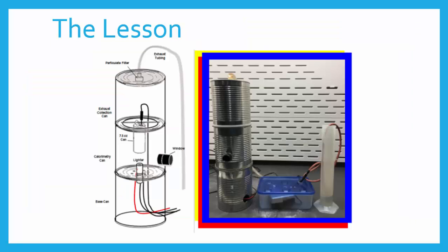Again, building off previous year's work, we developed a burner suited for the classroom in size and cost. It is fitted so that within one burn you can collect energy, particulate matter, and CO2 data. Pellets are placed on a lighter. While burning, a calorimetry can set above the pellet collects temperature data.